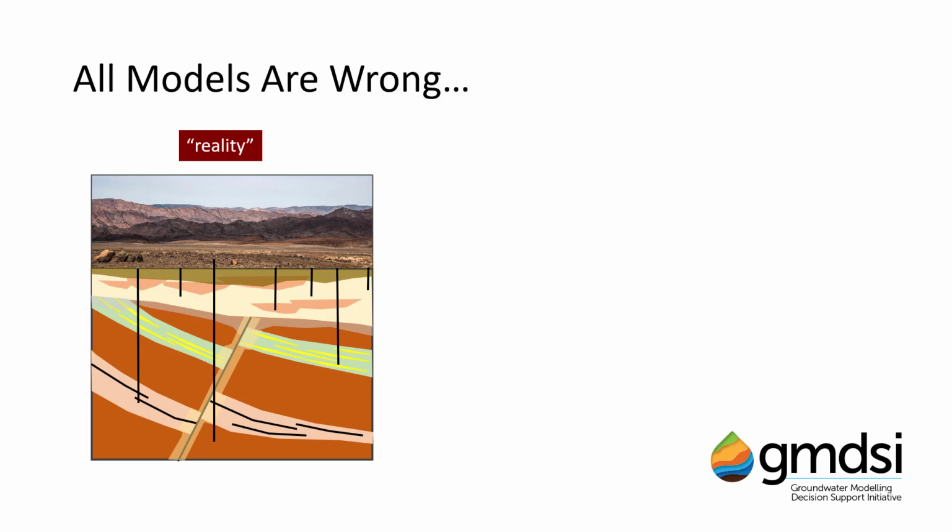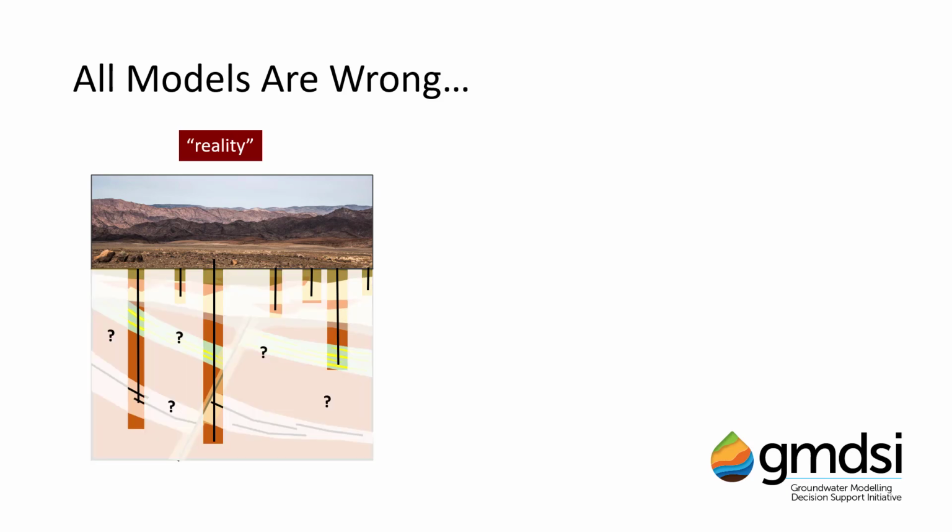So processes and properties interact across different scales, across multiple dimensions, most of which are at best measurable at discrete times and locations. Therefore, the data which we have to characterize a subsurface is so scarce that we end up having to apply a lot of interpolation or conjecture to essentially guess what occurs between these discrete observations. Even measurements of things such as heads or flow, from which we infer things about the system, mostly represent point samples and are, of course, also subject to errors and uncertainty.